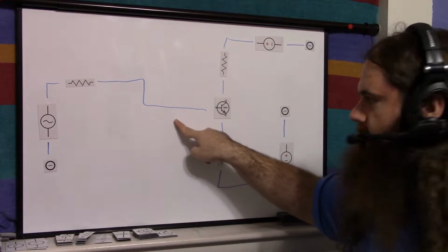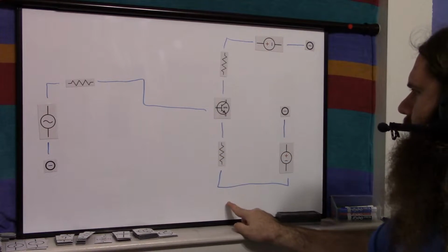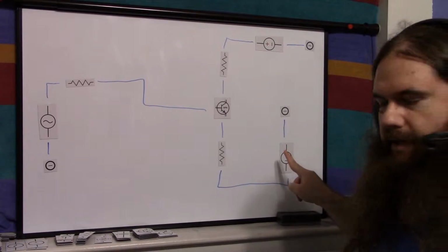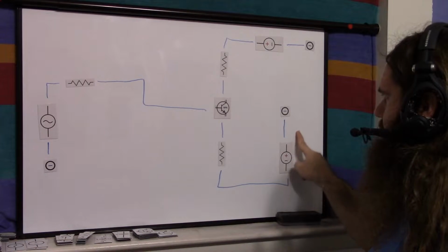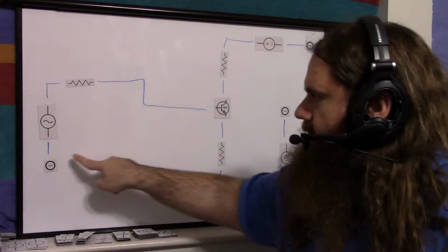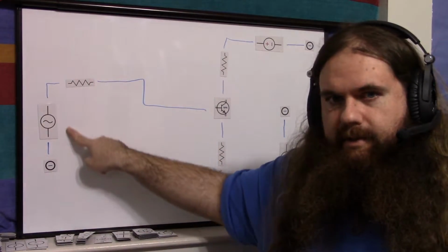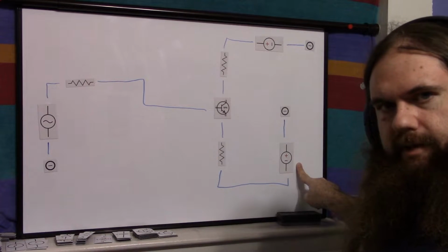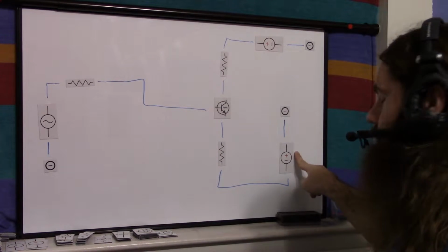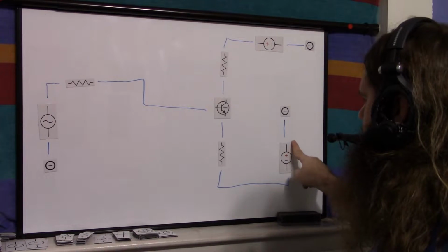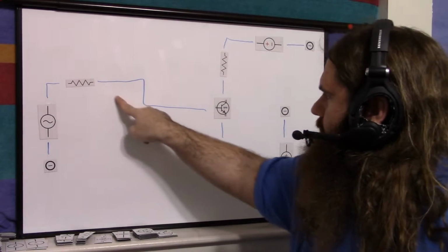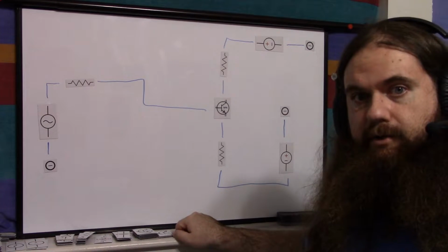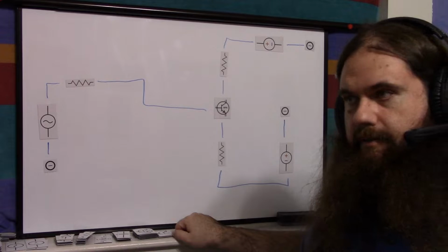So electricity is going to try to flow. And look at where you have your circuit. Positive, right? Because conventional current goes out the positive end. So you see out the positive end, to the reference voltage, which is connected over here, through the signal, which is at 0, through the resistor, through the base to emitter, and the emitter resistor back to the negative end of the power supply. So we have a loop from the positive end of a power supply through circuit elements in the proper direction to the negative end of a power supply. That's a normal circuit, isn't it? That's a normal circuit.